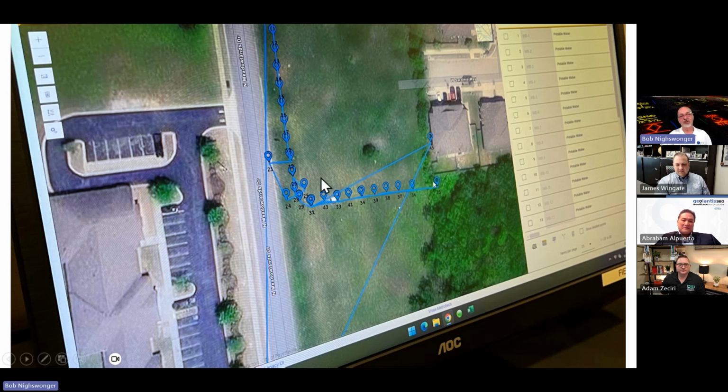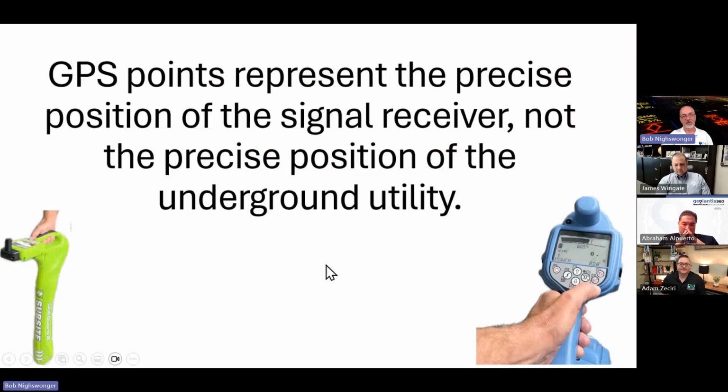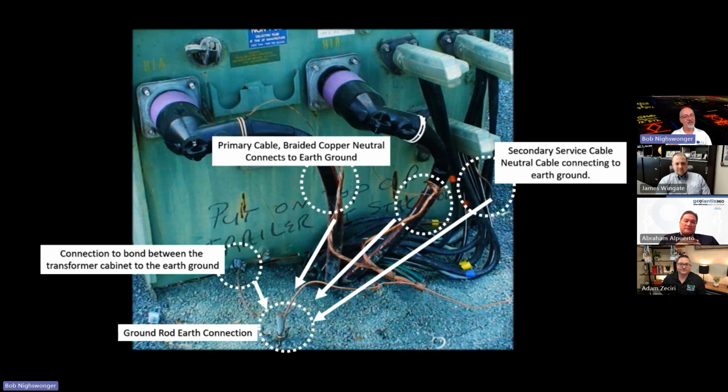Now, this was a current survey project, so there was a surveyor on site. So he thought he'd get a shot on that nail, and surprisingly, it was less than 1/100 of an inch off. But you can kind of see the line drawn when he starts going out of order. Ran over here for a valve, ran over here for a valve, came back here for these meters. It looks all scrambled. So we really need to be very aware that we are building a map now. Do these lines in order.